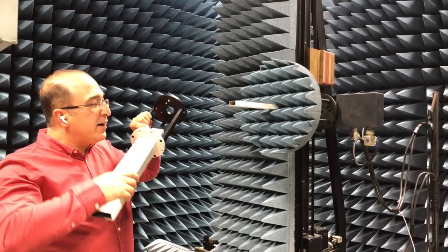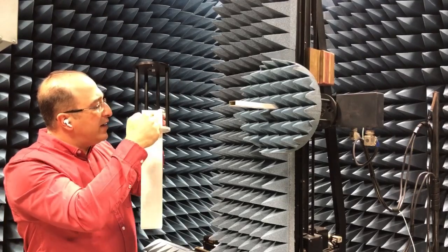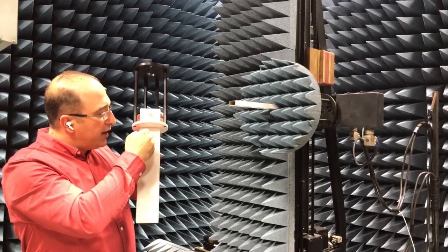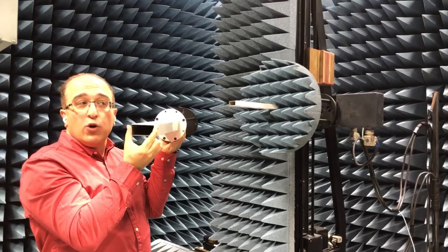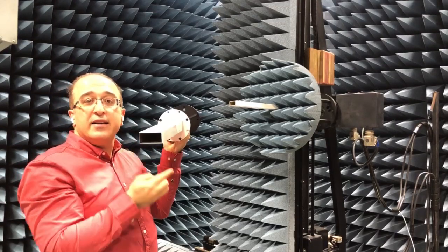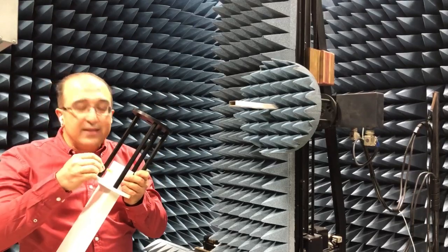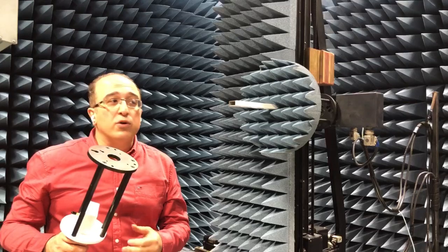And by the way, here you can also see the feeding point of this. So you can bring the energy using coaxial cable to the waveguide, and then it's going to travel. And now we keep the end of it open, and it in fact creates our open-ended waveguide antenna. So if I'm not mistaken, in the video related to lab 3 part 1, I'm talking about the radiation.